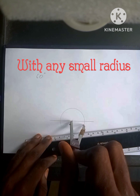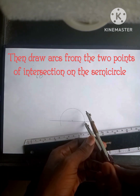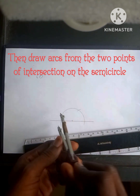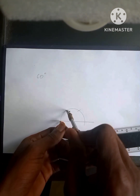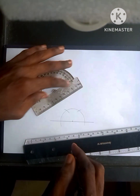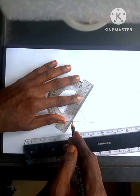After drawing the semicircle, don't forget the faint line. Put the compass at the first point of intersection of the semicircle and draw an arc. At the second point, draw an arc. So we take any small radius, put it at the point to draw a semicircle, then with that same radius, put it at the two points of intersection to get arcs on the semicircle. What we just did is divide 180 into 3. That gives us 60 degrees.